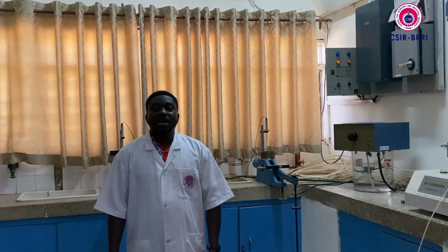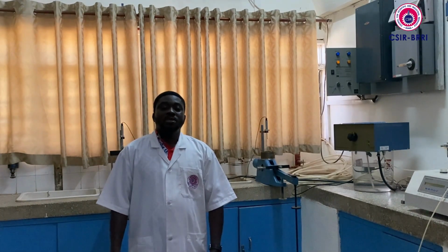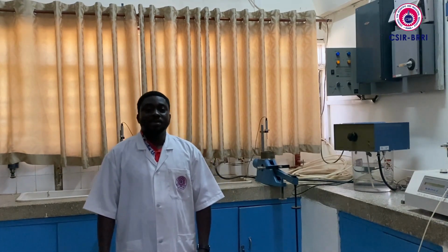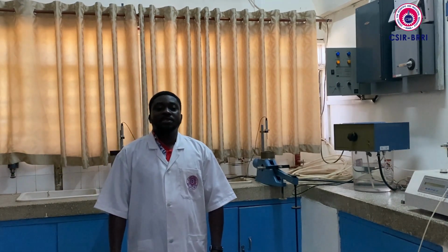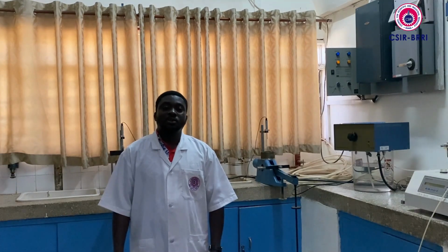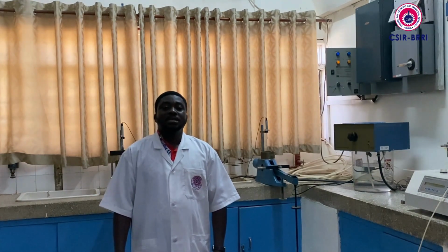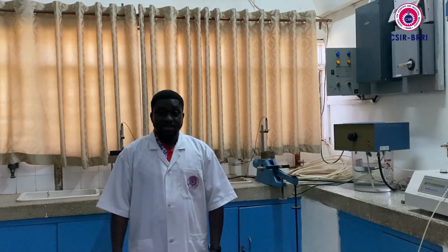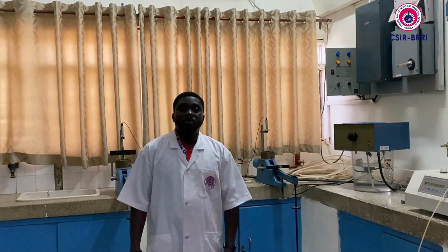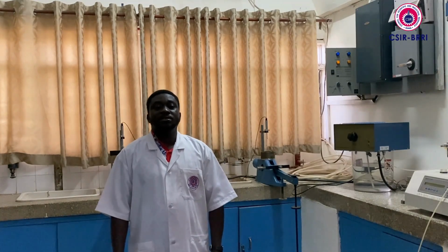Some of these factors may be a high groundwater table, which is the cause of building dampness that we witness in most of the buildings in our community. Another one is expansive materials that may cause differential settlement leading to building cracks. Another one also is deleterious materials like high pH, sulfates, and chloride content that are likely to affect concrete. That will lead to building collapse. So these are some of the factors that we unravel when we conduct geotechnical investigations.